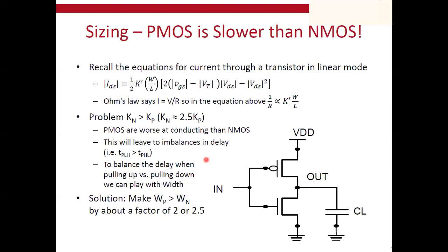Why do we need sizing? Why should we size our transistors? The answer is simple. In order to have this synchronization between the NMOS and the PMOS transistors, they both have to be on the same hand, or the same capability. But when we go to this very famous equation describing the current with respect to the biasing voltages VGS and VDS, there is a term here which, most likely in your previous courses, we considered to be some sort of a constant term,